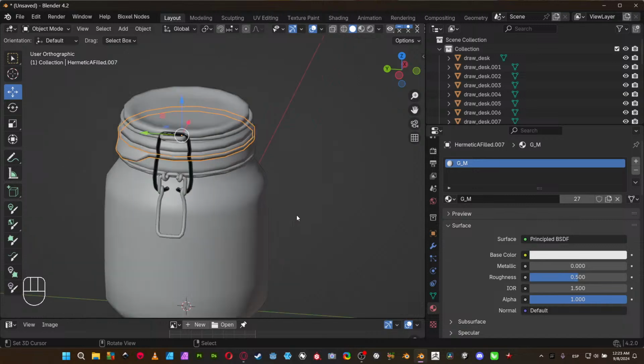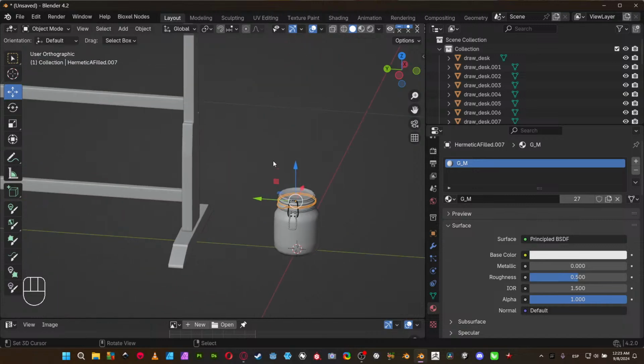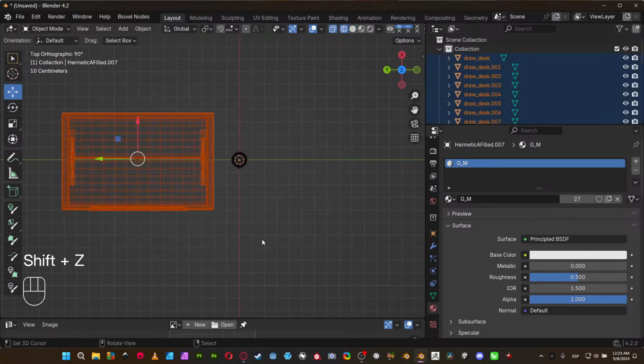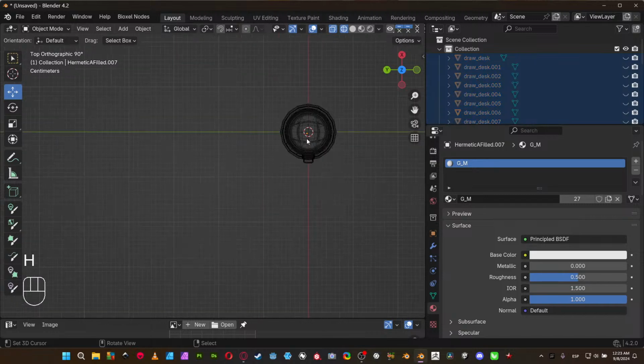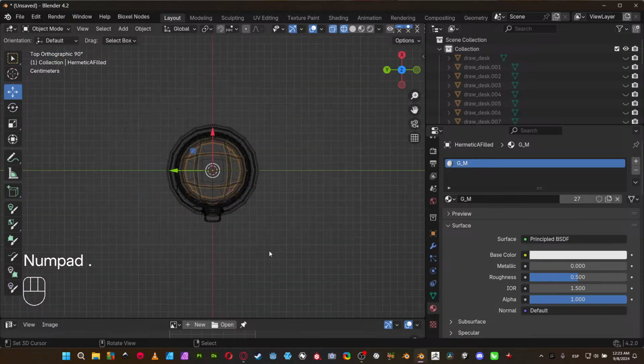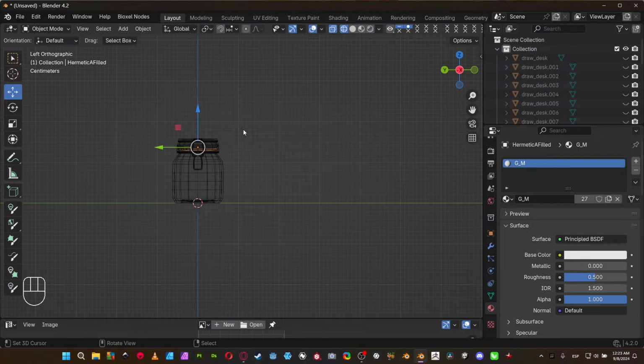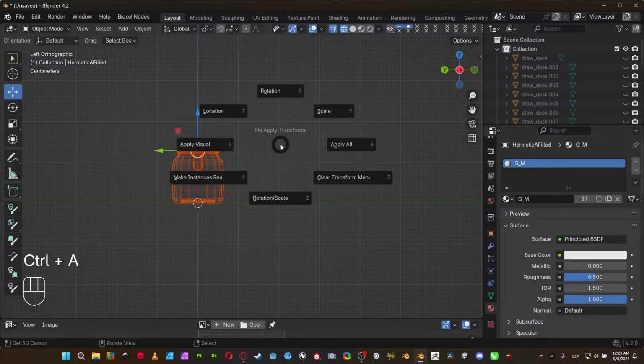First of all, guys, I'm going directly to the glass container with the pressure stuff in there. Mainly, it's not 100% a rule, but I really suggest that when you start unwrapping and UV mapping things, you select everything and be sure that all your transformations, scales, and rotations are reset.